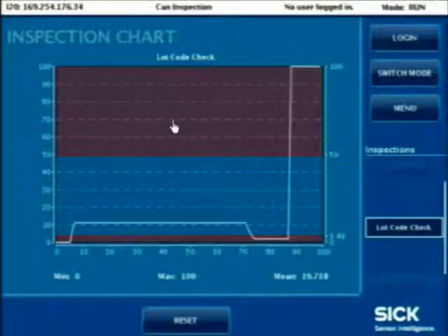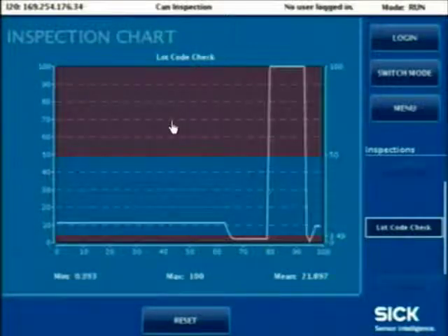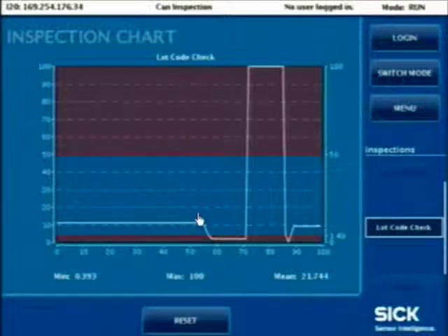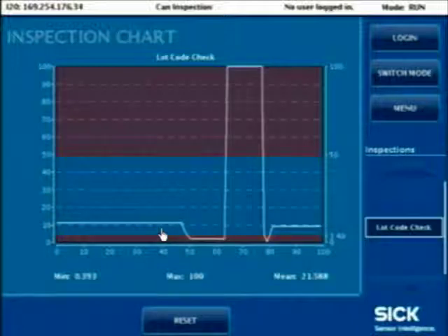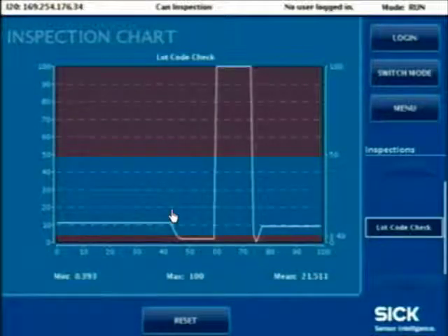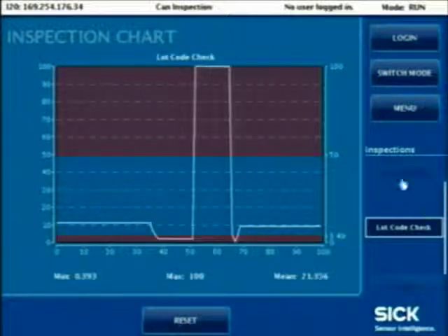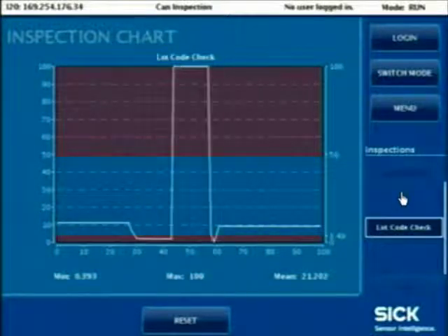This is a very useful tool because what the customer can typically do is they can have 100 good samples, 100 bad samples, and pass them underneath the camera and see what kind of thresholds are coming out for each of the inspections, and based on those results of the thresholds, we can then go ahead and tweak or configure our application to work more robustly in our own advantage. If we had more inspections available for this particular job, we should have been able to look at the charts for those inspections as well.